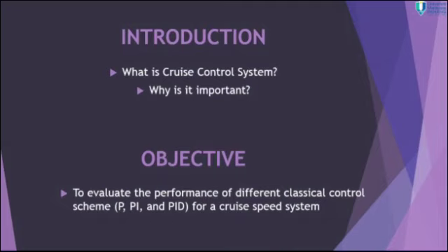Or we may want an aircraft to follow the desired altitude heading independent of wind gust and velocity profile. Or we may want to maintain at desired level the temperature and pressure in a reactor vessel in a chemical process facility. All this can be achieved by control method today without human interference, which is called an automated control system. This control involves the element of controlling the quantities, for example speed, altitude, temperature or voltage, in which this element needs to function in desirable manner over time.